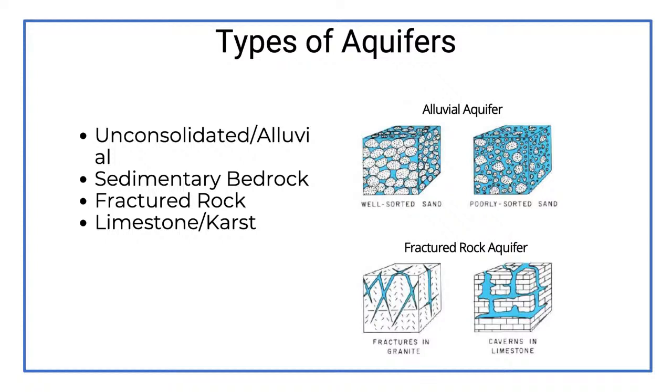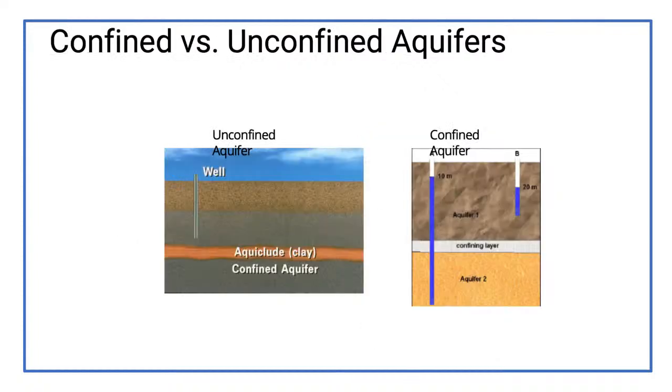An example of an alluvial aquifer might be the Central Valley in California, or you get over west of the Tennessee River in Tennessee. We start to get into the Memphis Sands and those type of alluvial aquifers. That's what I'm talking about. Fractured bedrock aquifers, you get up in granites, and you're going to mainly be dealing with fractures. That's just the way it is, and we're always looking for the fractures to find where the water is in those particular rocks. So keep that in mind.